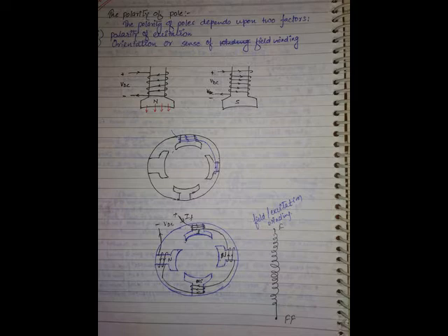The minimum thickness you can go to is only 0.35 mm, because the lesser the thickness, the mechanical strength of each sheet will be less. So you can't go beyond 0.35. Now, these laminations are stacked. Each lamination acts as an individual core to form one single core, and the eddy currents in each lamination will not flow easily. So you are reducing the eddy currents.